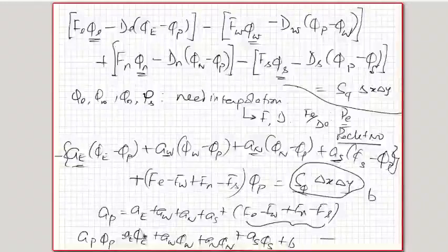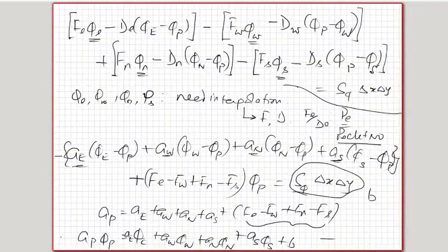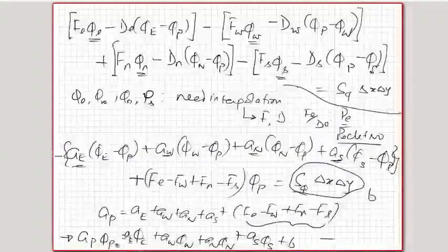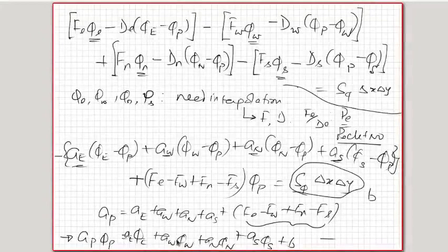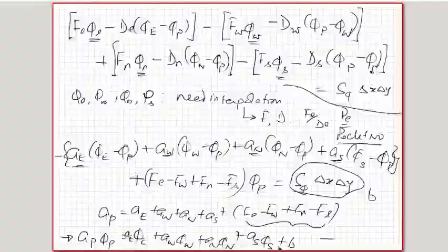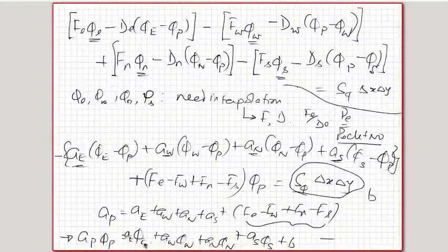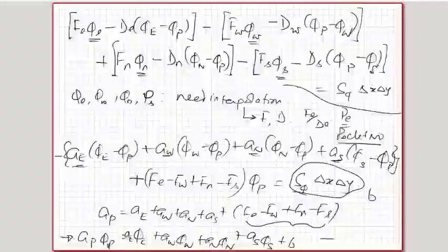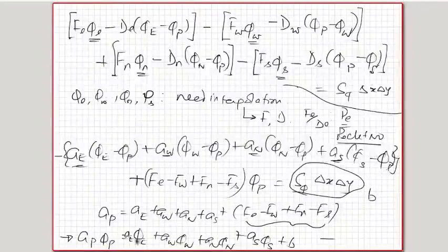So this is an equation where all the coefficients are written in terms of this. This is the way we derive equations, which are simultaneous linear equations in adjacent values of phi, and you get a 5 diagonal matrix in the case of 2D and a 7 diagonal matrix in the case of 3D, which needs to be solved in order to get all these phi values at all the grid points. So this is the method of solution.